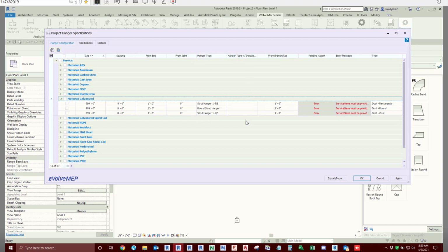Not something that probably messes with the ductwork guys a whole lot, but on the piping side, if our hanger is going over the insulation, you would need to oversize your hanger and add a shield underneath it. Ductwork, you guys just strap straight to the duct, so you don't normally have to worry about that, I don't think. Maybe when you're outside, like on a roof, and you have some hard rigid fiberboard on the outside.